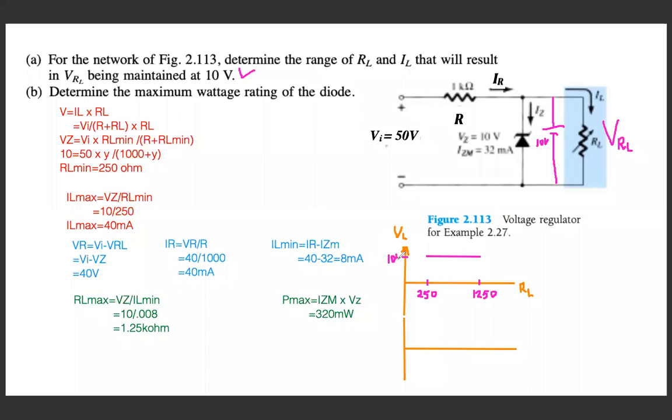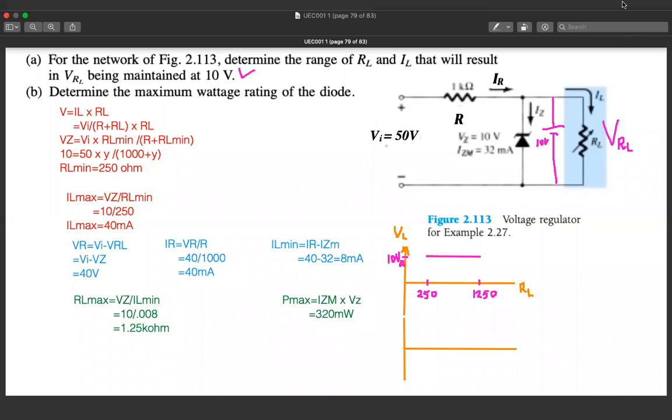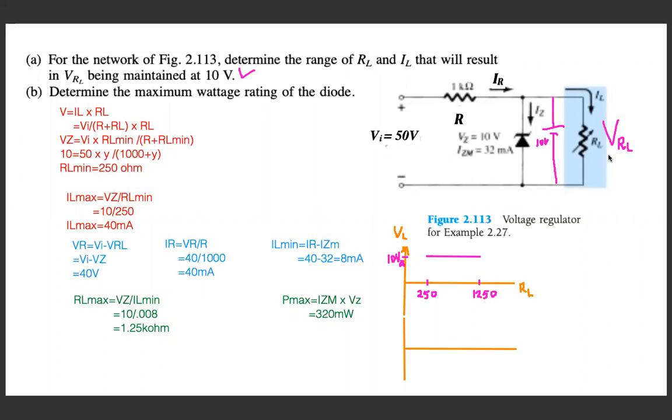Because that's why we were doing this using the Zener diode, to regulate the voltage across the load resistance. We are using different kinds of appliances in the home, and if you are using a simple electrical device, then depending upon its temperature, its functioning, how much longer we are using it, the current flowing through that load resistance, that device, keeps on changing. But we do not want to change the voltage across that device. We want to keep that within the specifications of the device. That's why we use the Zener voltage right here.